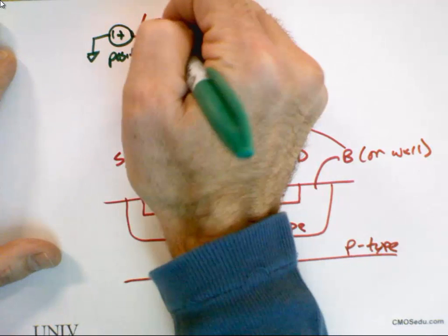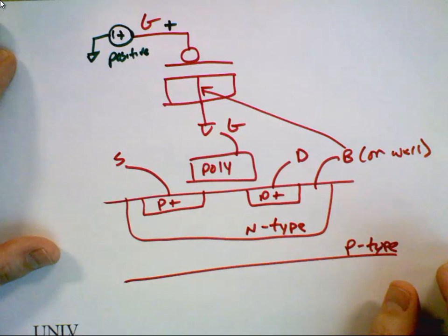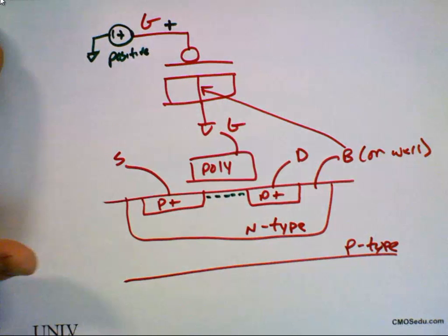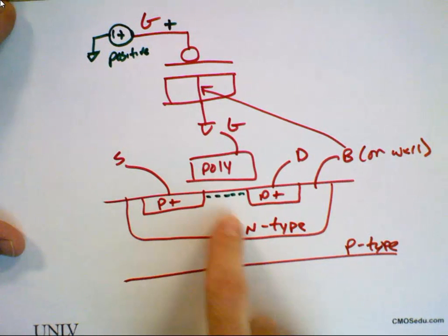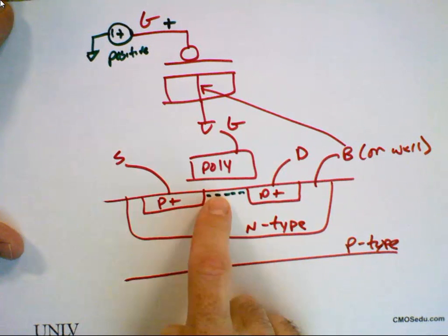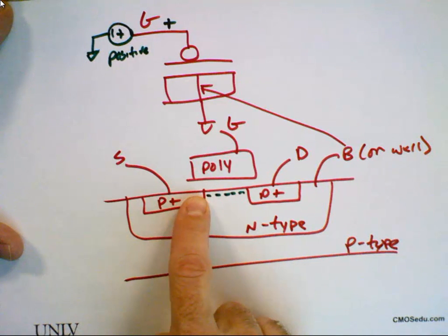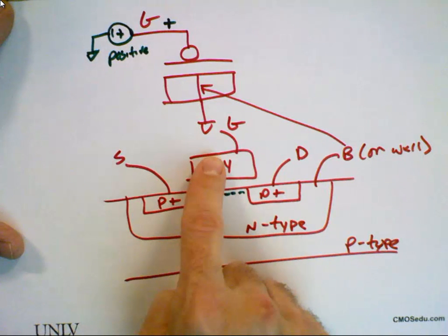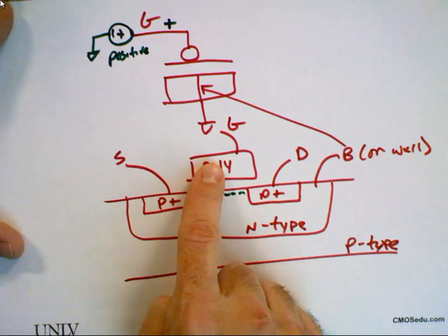So we got a positive potential there. And what do we attract underneath the gate oxide? Electrons. What do we say about that underneath the gate oxide? It's an accumulation. Those electrons are the same polarity as the body. They're both N-type. So the surface is accumulating electrons. And we can go through the exact same discussion of lateral diffusion, effective length, all that stuff, and calculate the capacitance to be the same thing as Cox.